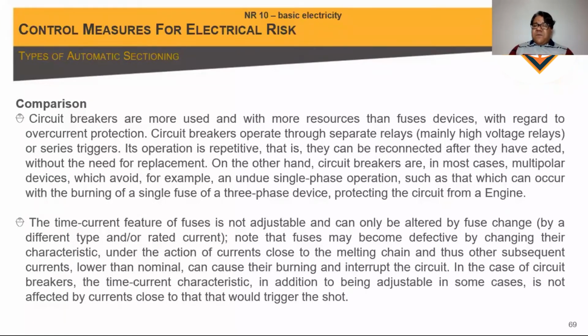They are rearmable. On the other hand, circuit breakers are in most cases multipolar devices, which avoid, for example, an undue single-phase operation, such as that which can occur with the burning of a single fuse of a three-phase device protecting the circuit of an engine, for example.